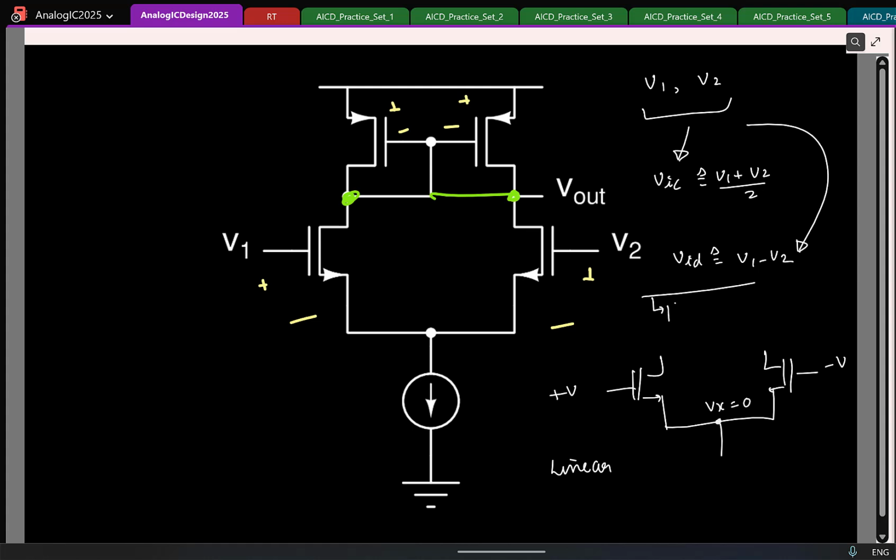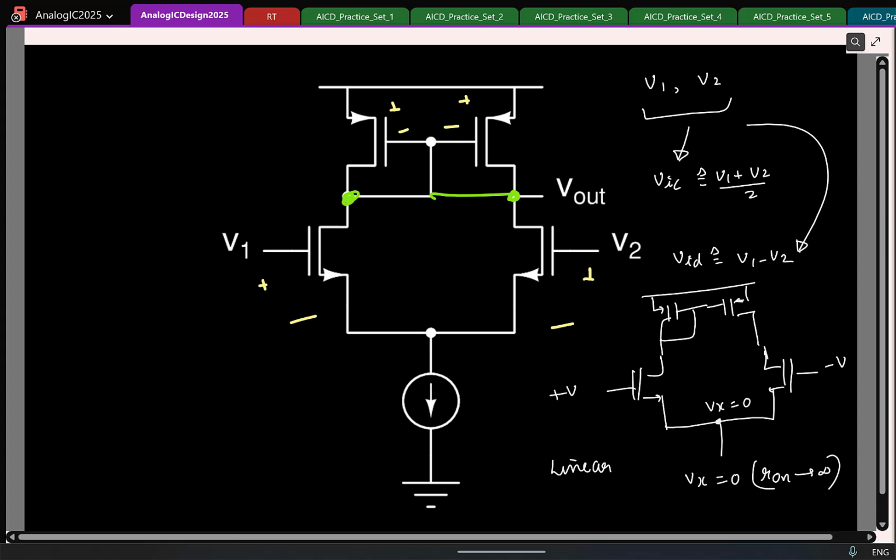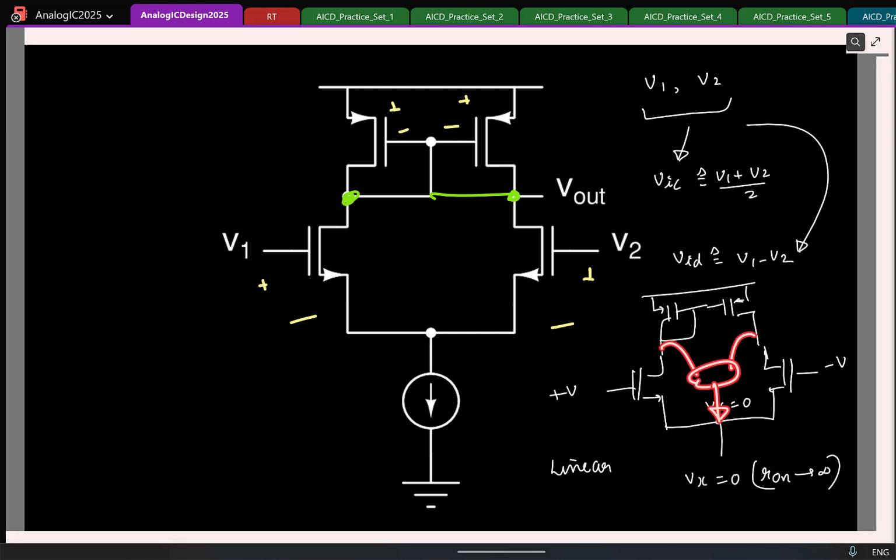And we also noted that even though we might have asymmetry here, when can you argue that Vx is 0? Yeah, if we ignore the R0 for the NMOS transistors, we can say, because again the reason is the asymmetry is at this node. It is the R0 of the transistors which couple this asymmetry to this node. So if you get rid of them, you are fine.